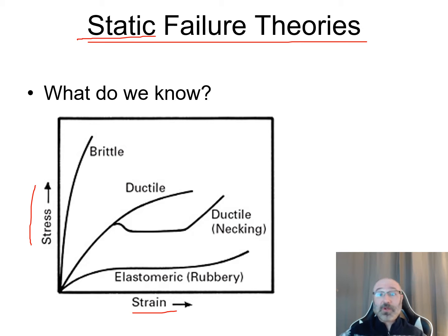So a lot of times we're doing a typical tensile test right there. We get our raw data in that force displacement mode right there. So with that there, with our dimensions, we can go from there and create our stress strain curve with our basic equations right there for stress and strain. We can use that information from dimensions, our force, and our displacement as well. From that raw data, we come up with a curve that looks like this. And in particular here, let's take a look at the material and like, is it a brittle or is it a ductile material? And within that there's a couple different options there.